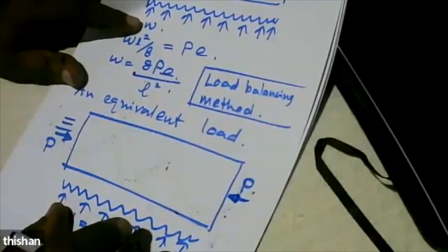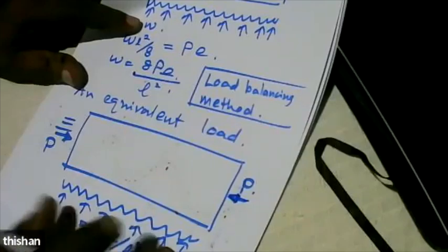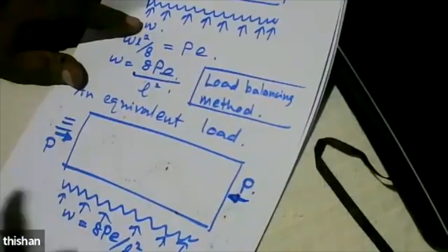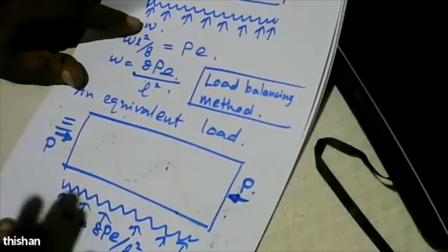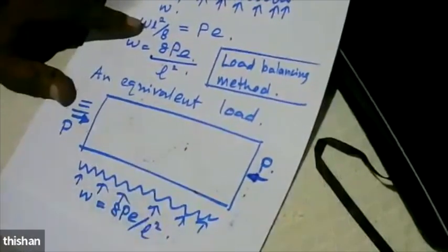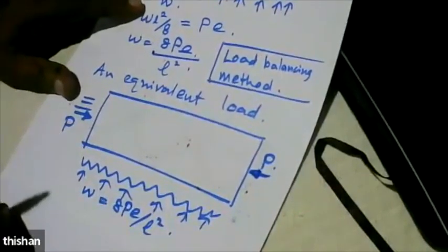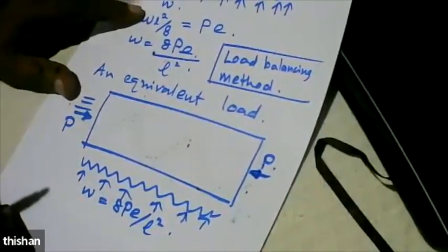They always look at pre-stress concrete as, when you have a parabolic cable, it is like applying a force upwards. The effect of this is applying a force upwards. So this is the method that they use in United States.